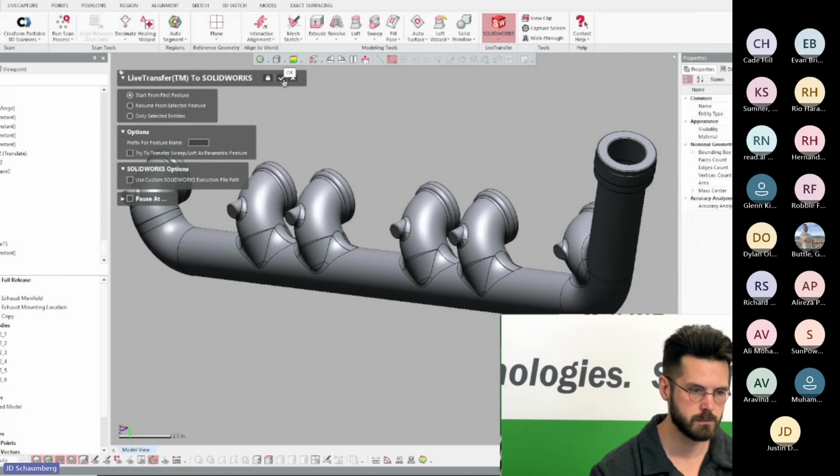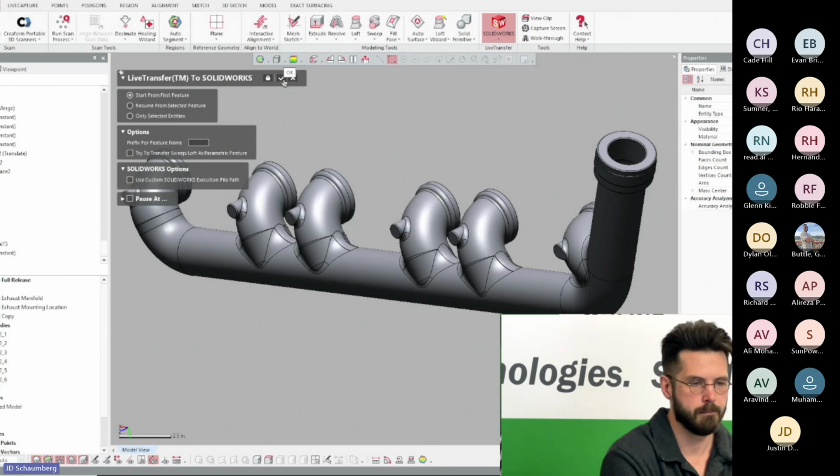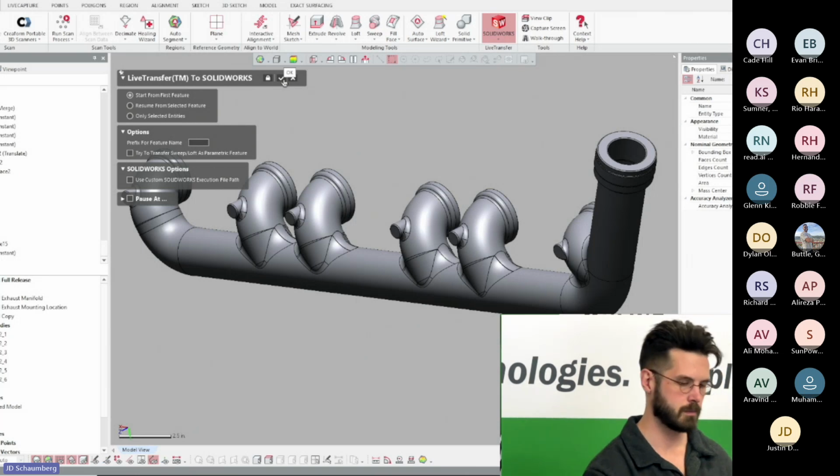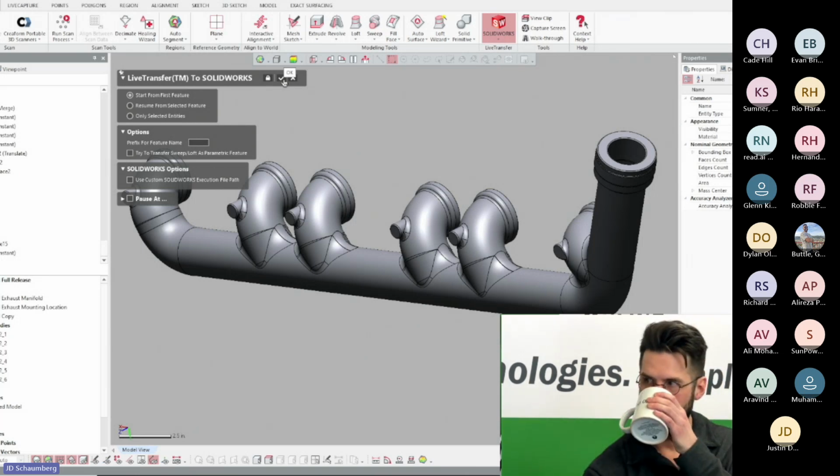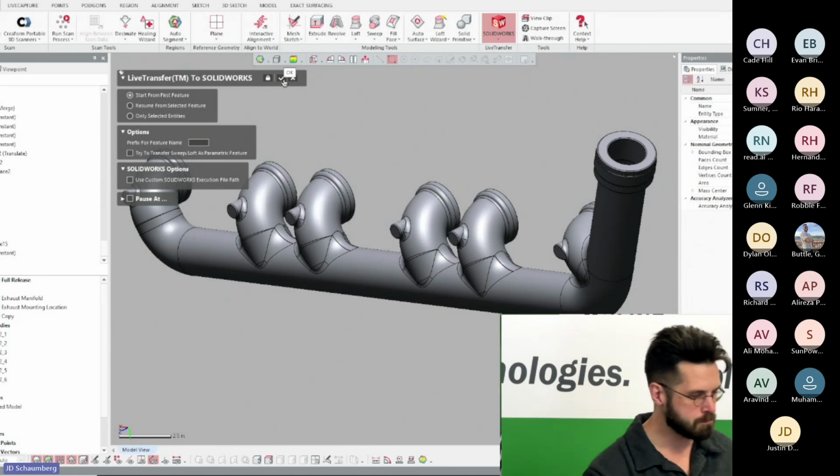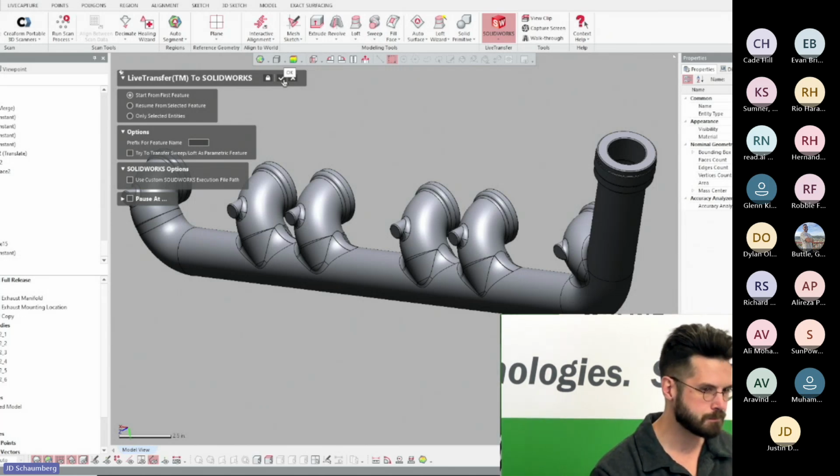Yeah. Cool. That is a very powerful tool, especially when we're doing some service work for somebody and they don't have Design X to go back to. We call that a smart model, something that's editable. And when we just export, like a STEP or Parasolid, we usually call that a dumb model, because they can still interact with it and do their basic cutting. Like they can cut it in half, or they can add to it, like add bosses.